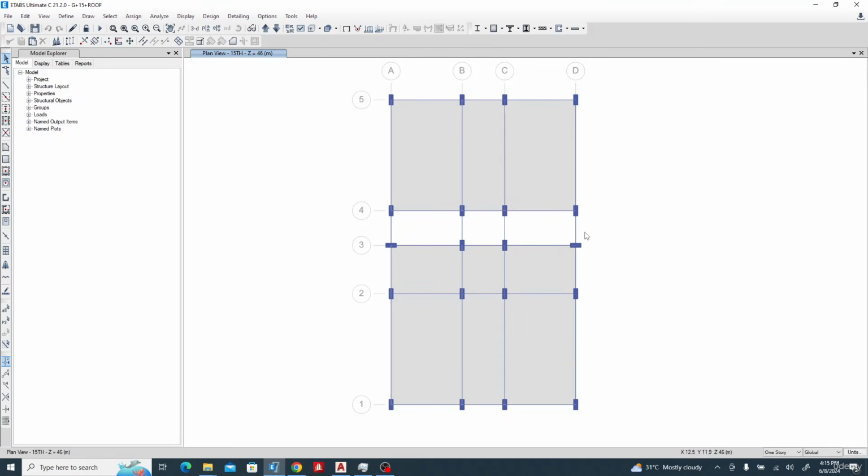So now what I want to do is place a cantilever slab along this side. So let me bring out my beam, and let me say my cantilever slab is, let's see, 1.2 meters. So I have my offset 1200. Now I can draw it from here and place it here. If I come like this, it's going to come in this direction, but I don't need it. So I have this beam here. So all I'll do is draw my slab. I'm going to make my slab 175, and I will bring it into this point.